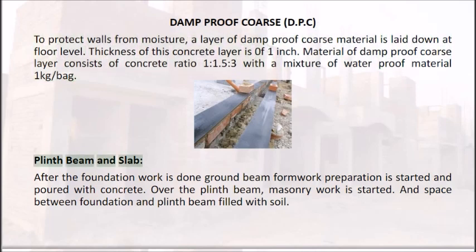Plinth beam and slab. After the foundation work is done, ground beam formwork preparation is started and poured with concrete. Over the plinth beam, masonry work is started, and space between foundation and plinth beam is filled with soil.